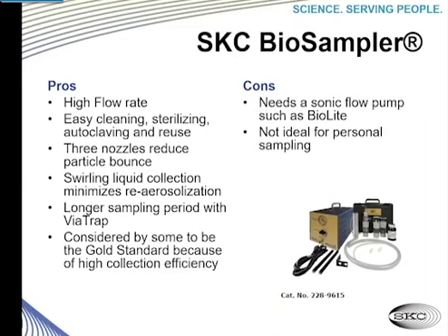The cons: you need a specific sampling pump with sonic technology, such as the BioLite that I mentioned. And it's not ideal for personal sampling due to the size of the sonic pump. I mean, this pump is big. It's typically used for area sampling.